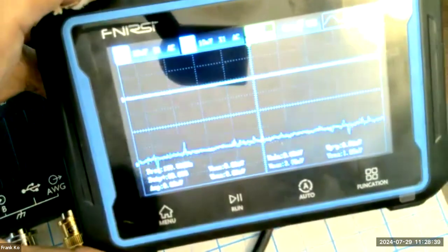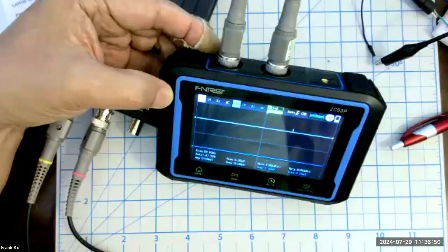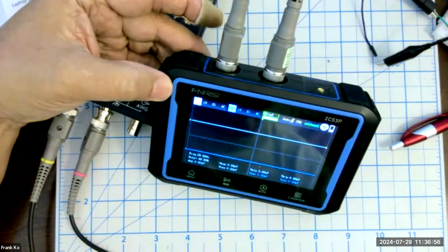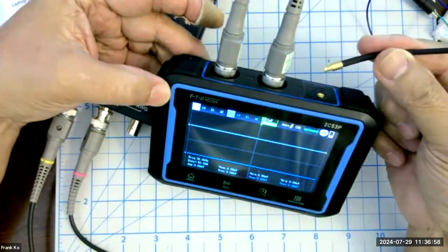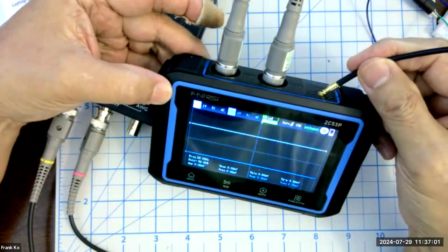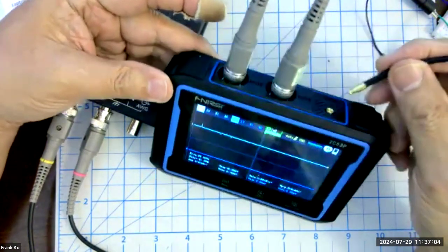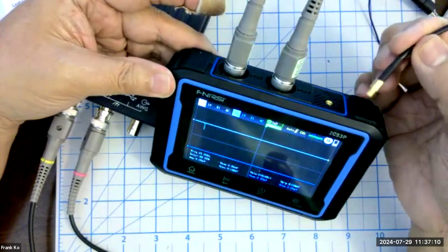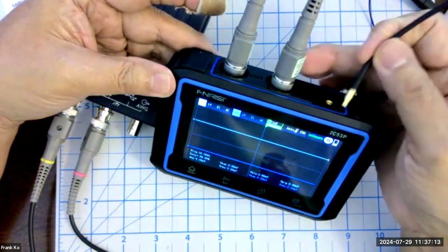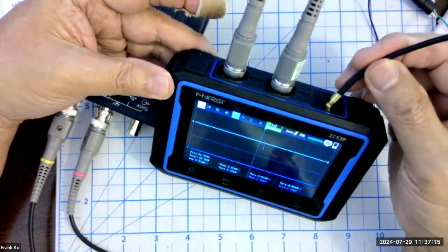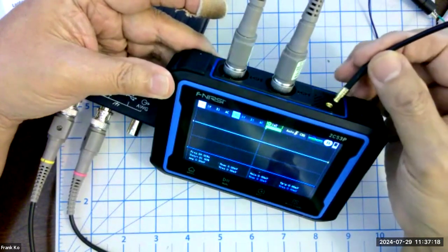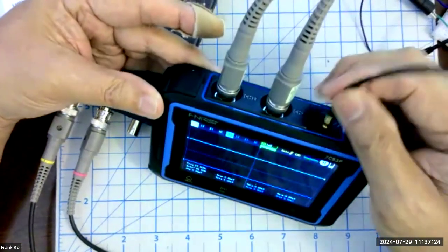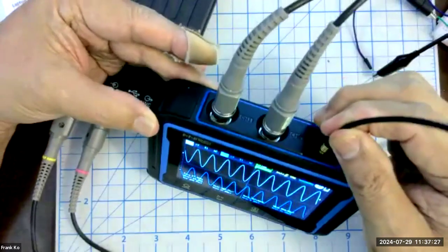So I'm using a slightly different signal generator. Hold on. All right, I'm going to use the designated micro BNC connector. That's this guy right here, to the signal output of the function generator portion of the tablet. Take this and be very careful with this, because it's going to be hard to replace if you damage this particular cable. It's not a standard BNC like the rest of these. Would have been nice if this was a standard BNC, but it isn't. It's okay. We will just be very careful. Take this and carefully plug it in. Push straight down until it clicks.